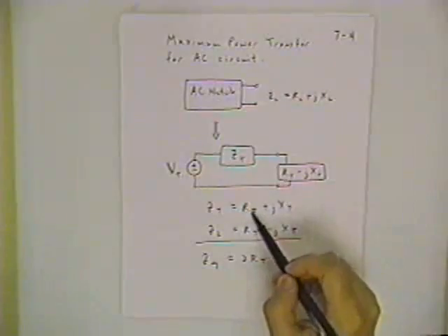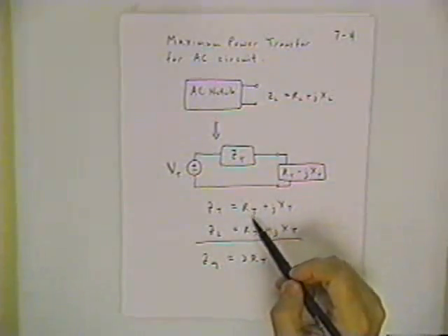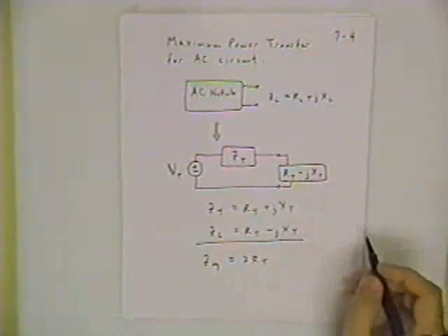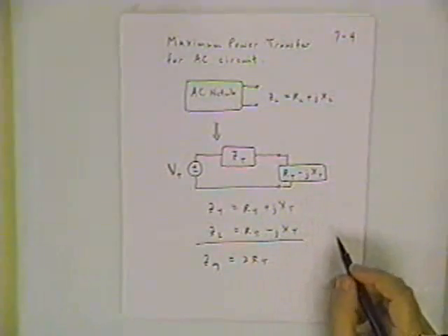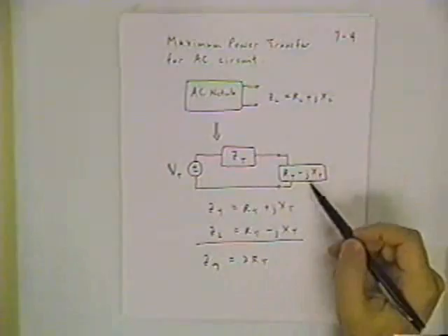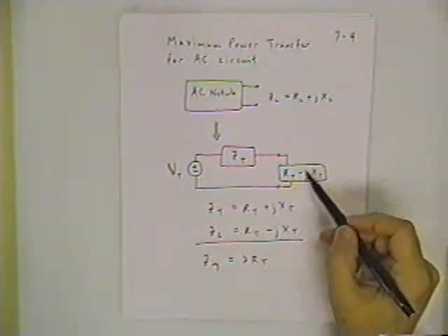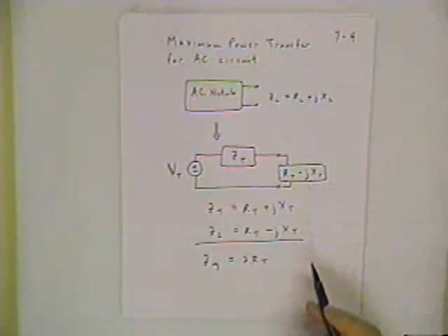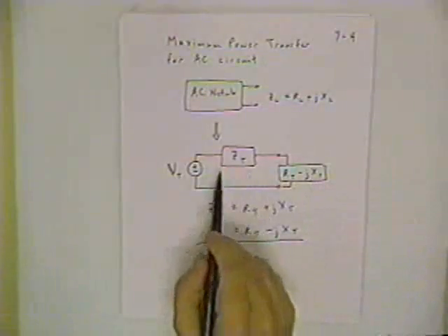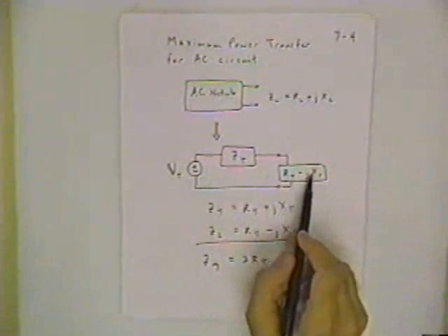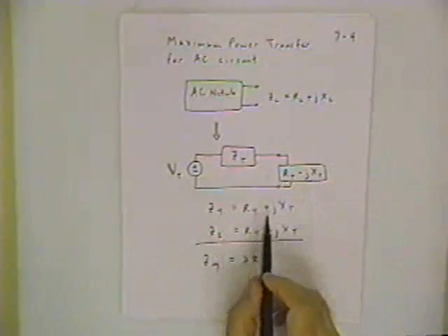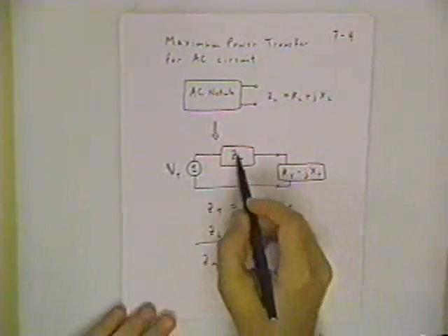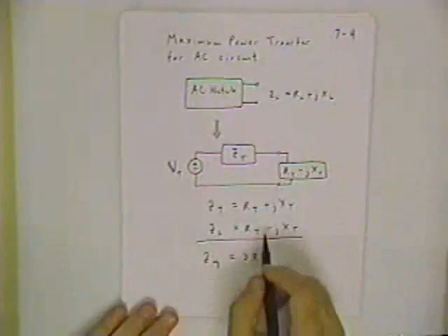It's the resistive part of the power that delivers sound to speakers and delivers force to motors that are turning. Anytime you have a non-zero reactive part, that means you're losing a little bit of your energy to trapped energy in the elements. So to get maximum power transfer, you want to get rid of the X part, and you do that by attaching not the Thevenin equivalent, but the complex conjugate.